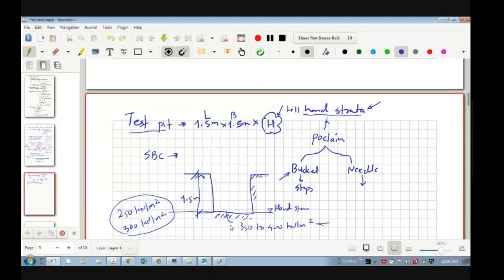If you ask me, I will take these values as per my experience. But if you take the decision, don't go beyond this unless you do many projects and get a feel for the numbers. So you see the geotechnical reports given by the geotechnical people. Then you can understand that this was the strata and for it this SBC came. So you can study the strata through the geotechnical reports, and if such a situation comes, you can take decisions like this will be 300, that will be 350.